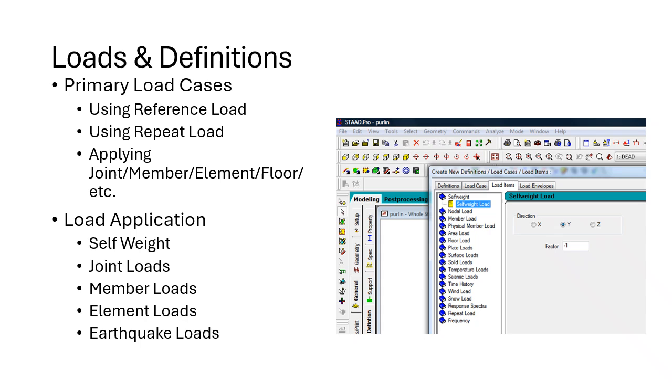And here comes now the load definition. First we create different load case names, and STAAD has one more capability they call reference load. Reference load we define at the beginning, and for that it will not solve the matrix. Like what it is using, the stiffness method. In the stiffness method, the software will first fix all degrees of freedom, and then it will try to solve. So that's what we call the stiffness matrix, Kx equals F. And there we are finding displacements.